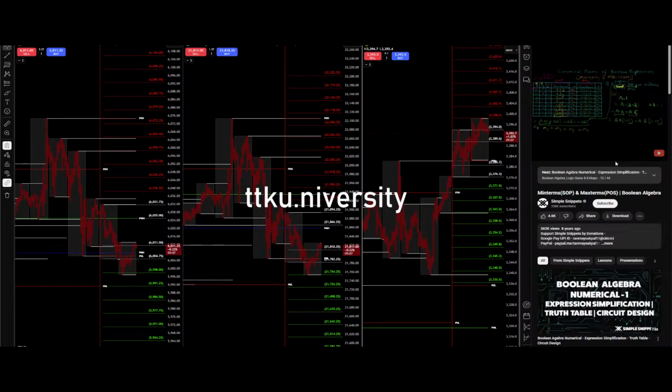So this is how I represent a Boolean function in its canonical form of min terms. This can also be written as f is equal to just these values, which would give us summation of 7, 6, 5, 4. The reason why I wrote the summation sign is because it is sum of products.